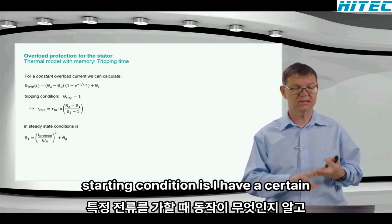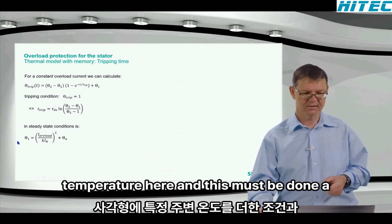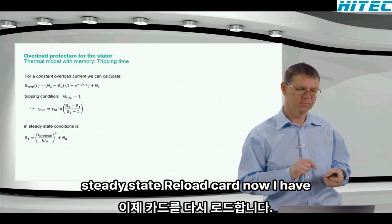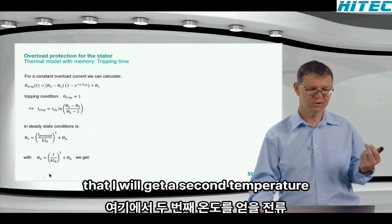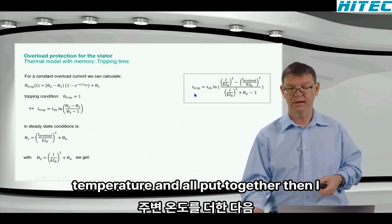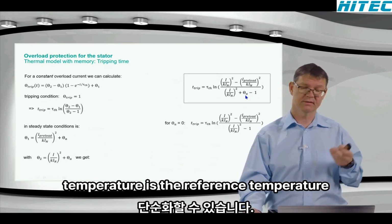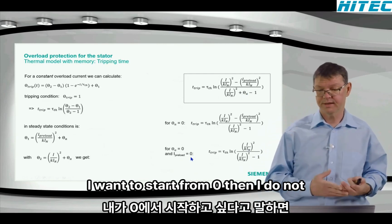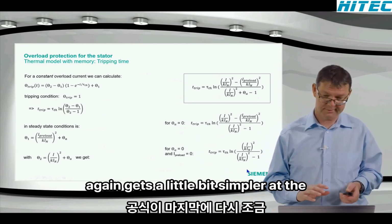So the starting condition is I have a certain preload current to the square plus a certain ambient temperature here. And this must be then a steady state situation. And I get a certain temperature with a certain steady state preload current. And now I have suddenly another current, a current jump. Then I will get a second temperature here depending on the higher current or lower current plus the ambient temperature, and all put together then I get this formula here with a tripping time. I can simplify that. If my ambient temperature is the reference temperature, then this theta A goes out. And if I say I want to start from 0, then I do not consider here the preload. So the formula again gets a little bit simpler at the end.